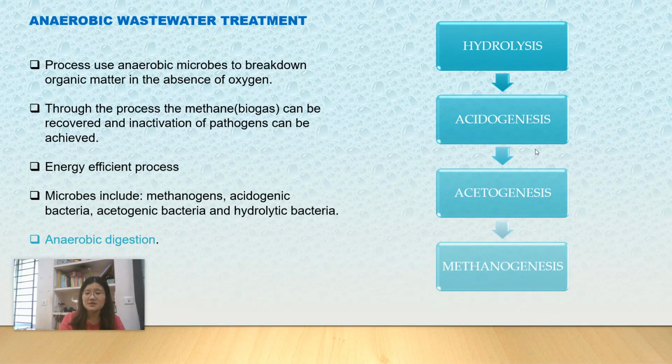The last step is methanogenesis, where the byproducts of acetogenesis, which are acetate, carbon dioxide, and hydrogen molecules, are further converted into methane gas and carbon dioxide with the help of methanobacterium. It's the final energy recovery step where we get our renewable energy, which is our methane.